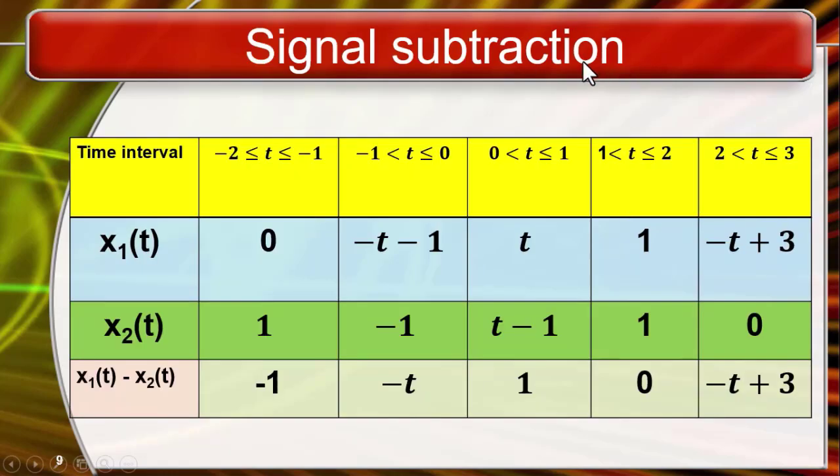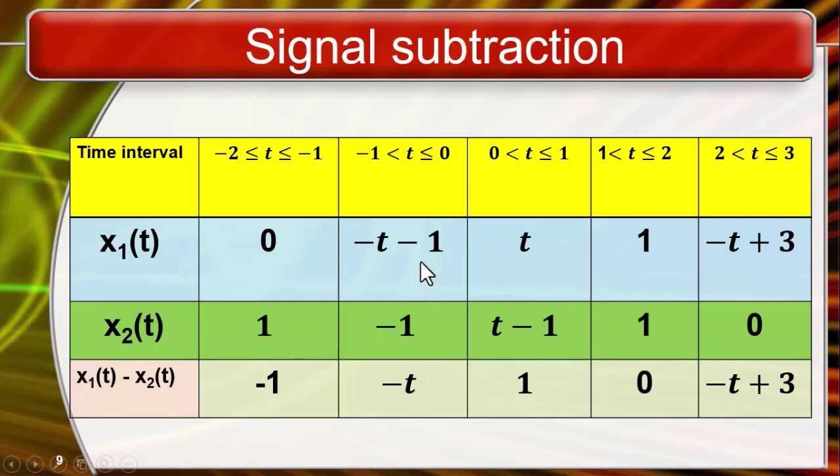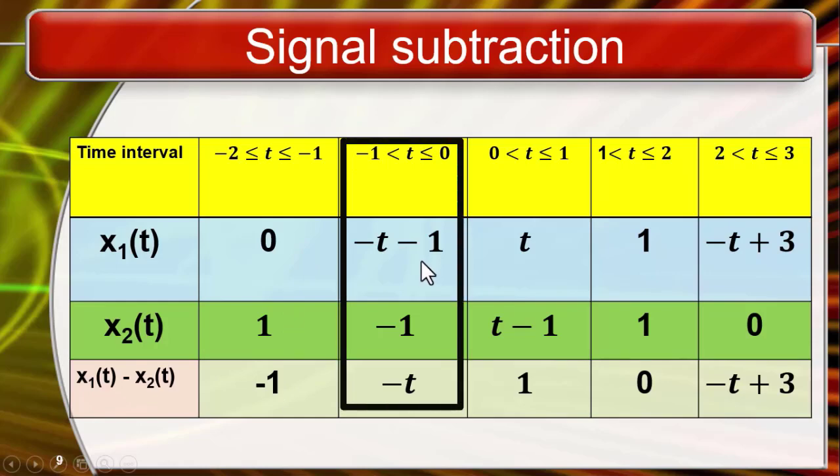Let x1 of t and x2 of t be two continuous time signals. The difference between x1 of t and x2 of t can be obtained by subtracting x2 of t from x1 of t at every instant of time. So here x1 of t is 0 and x2 of t is 1, the difference is -1. And here x1 of t equals -t minus 1 and x2 of t is -1, their difference becomes -t.